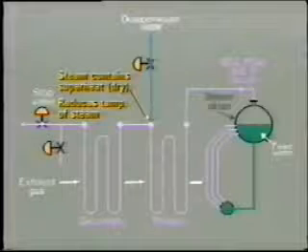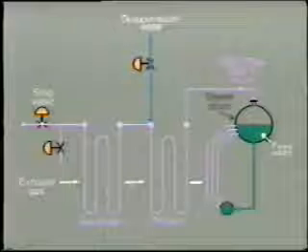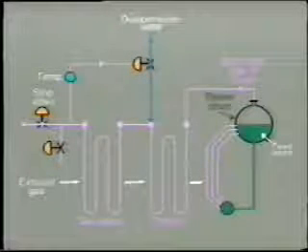The steam here already contains a considerable amount of superheat and is therefore dry. The de-superheater water is quickly evaporated into steam, but in doing so, it reduces the temperature of the steam entering the secondary superheater. The quantity of water injected into the de-superheater is controlled by monitoring the final steam temperature as it leaves the HRSG. Steam temperature control is often referred to as attemperation. It becomes very important where high gas temperatures exist from the gas turbine or from a fired section.